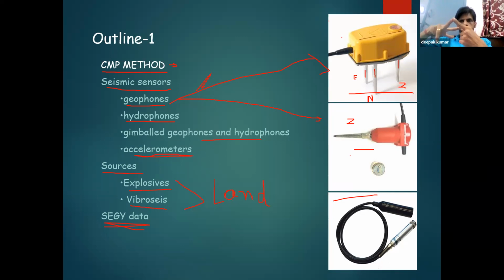So it is for recording earthquake waves for vertical, northing and easting. We took the same concept to make a 3-component geophone. It acquires data in 3 perpendicular, orthogonal directions. This is vertical, and this will be the northing, always pointed towards the geographical north, and this will always be pointed towards the geographical east. So the data will be recorded vertically, then in the northing and then the easting. There are 3 sensors orthogonal to each other, and all these sensors will record the particle motion in the vertical direction and the northern and eastern directions.